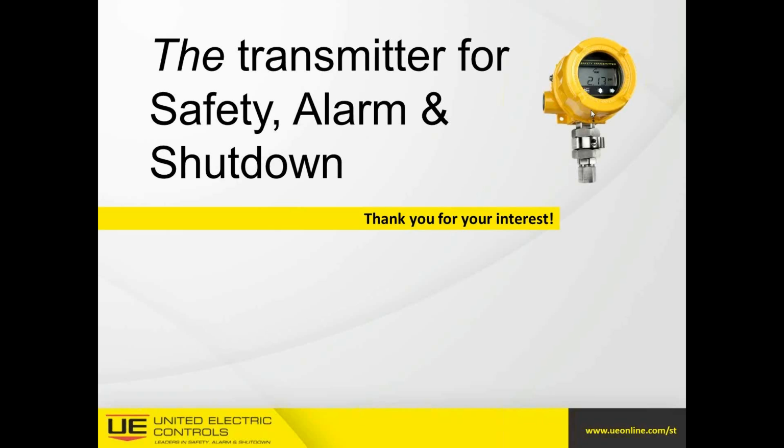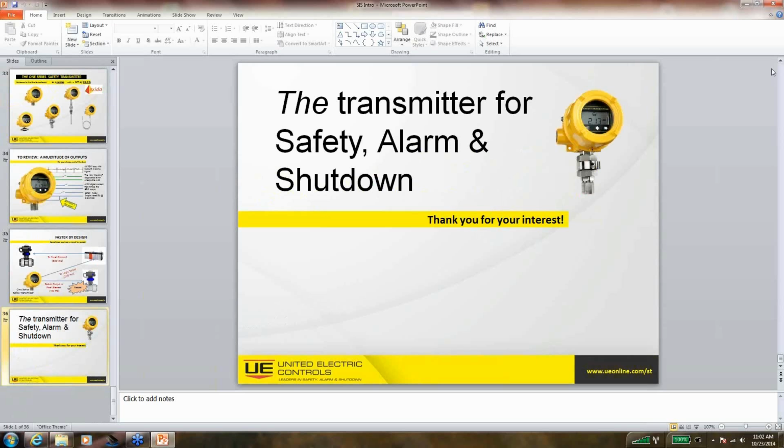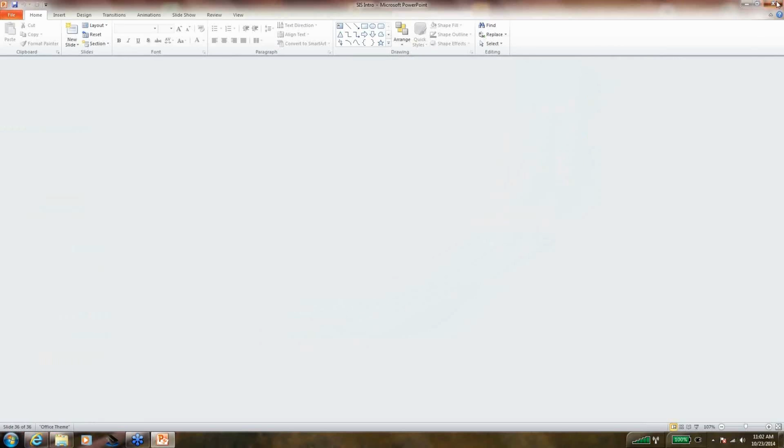The last question we have is about the combustion control systems. Sure. And here's the question. The basic process control system would be considered a combustion control system. And yes. Okay, so we got that piece. And the SIS would be considered the burner management system. Yes. Okay. If you want to flip the screen back to me, I just pulled up the Honeywell Flame Safety Relay to show people where you find the SIL information.